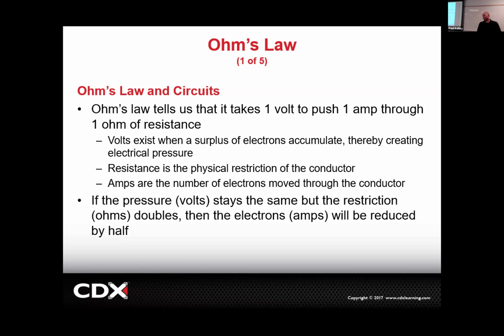If you were to look at a battery and measure from the positive and negative and get 0, it doesn't necessarily mean there's literally 0 volts. It means there's no voltage difference, right? So just picture your meter as telling you the difference in electrical pressure between the red lead and the black lead.